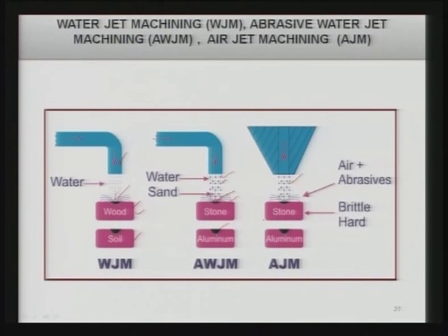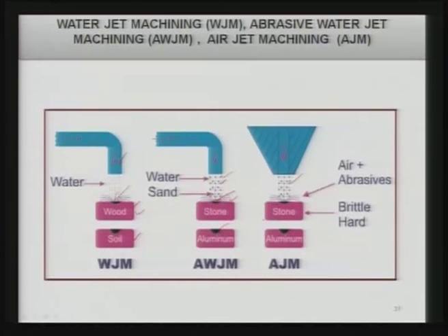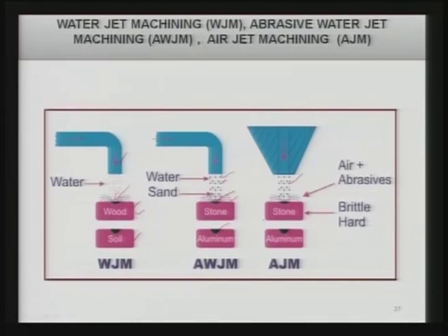Now, the question arises: in these last two cases, abrasive particles are acting as the tool and they are able to remove the material, but when we are taking water and sand particles, how are they able to remove the material? So, by taking the philosophy, the idea from these two phenomena, one could think, can we make constructive use of these phenomena to remove material from engineering materials? So, taking this kind of idea from these processes, quite possibly people must have developed the processes known as water jet cutting, abrasive water jet cutting or abrasive jet cutting.